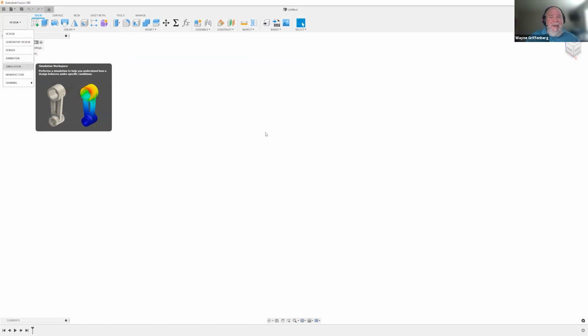Simulation, this is our FEA. This is actually NASTRAN that's running in the background. Again, as we're fusing those pieces together, this opens up simulation where you can do some stress strain analysis, modal frequencies. You can even use this to take a look at the tool, like tool deflection, or even see forces on your tool. And it's outside of CAM, but at least it gives you some insight on where you'll see most forces, and you can probably even change your tool length offsets and such according to simulation.